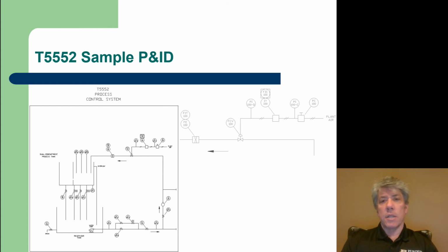Now, in this context, this is not an automatic control in the sense that it's some type of a PID controller you're going to tune. PC, what they mean here is this is probably just some type of pressure reducing thing. So you would likely set it with a hand knob so that whatever pressure you want is indicated by PI 100-C, and that takes plant air down to the pressure that's needed for the process. And so IY is something that likely would be measuring current, because I is the most common thing is current.